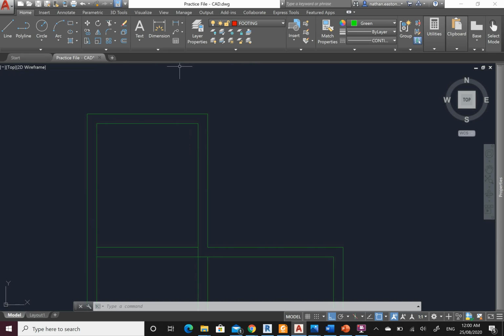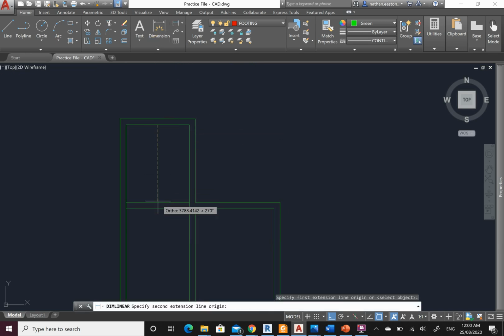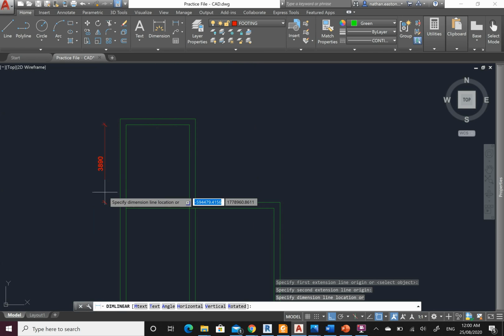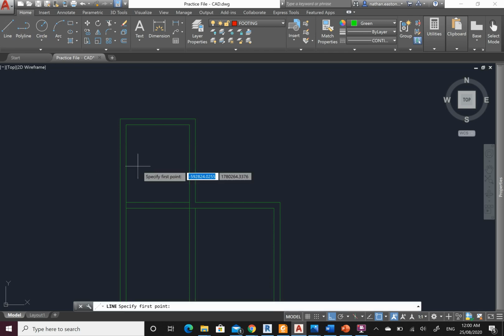Let's check this one up here. It's the first footing coming in, and it is too big. Okay, from center to center is more than 4 meters, which means we have to put one in the middle. So deemed to comply, we have to do this.